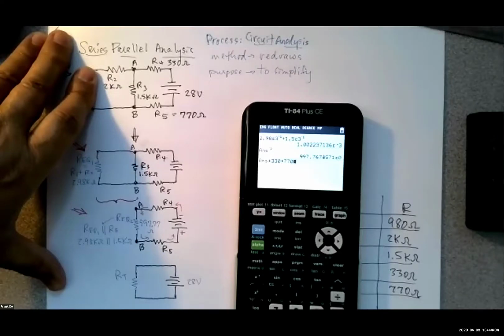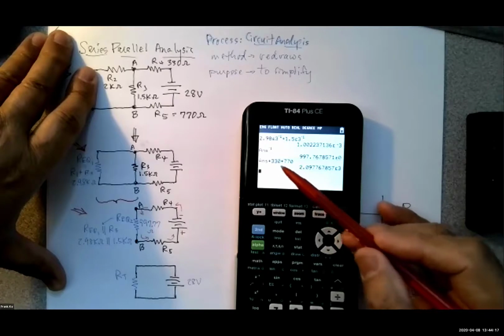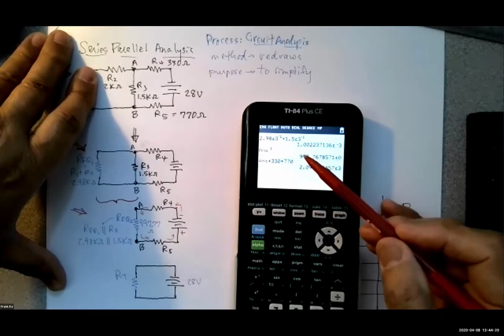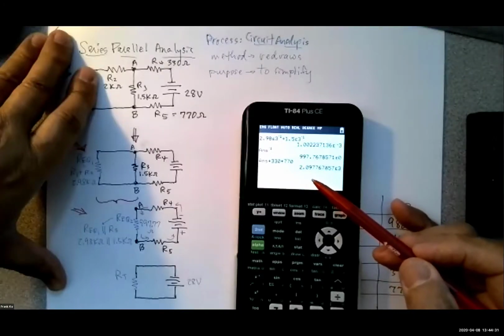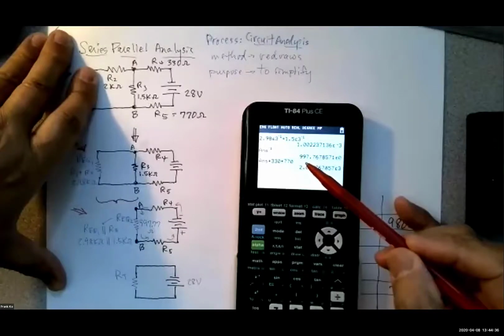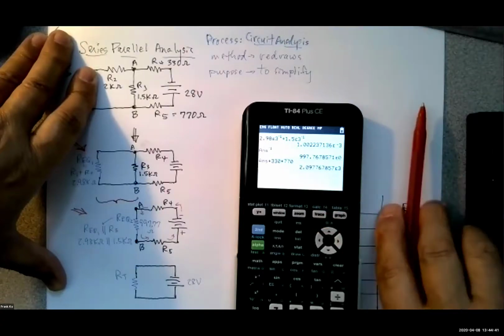How many people agree with 2.83 kilo ohms? Let me hit enter and see what happens here. Yeah, I won't quite get that because this is less than 1,000 and these guys come up almost 1,100. So I end up with less than 1,000 plus 1,100 should be something less than 2,100. Yeah, I got 2.10 also. So this will round out to be 2.10 kilo ohms. So Pauline, you're adding 997.77 plus 330 plus 770.